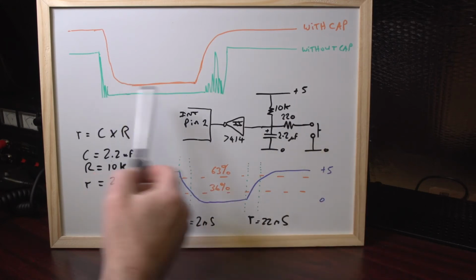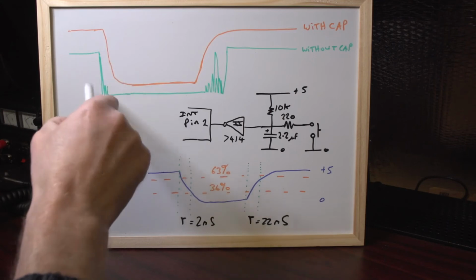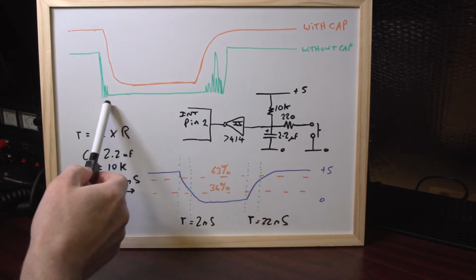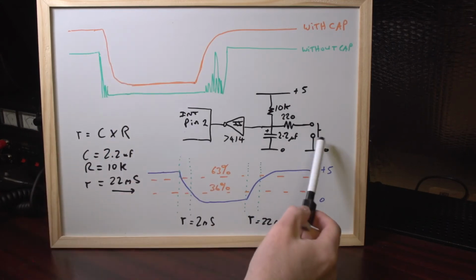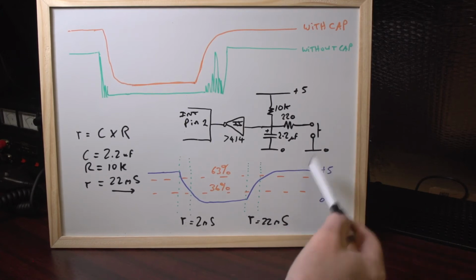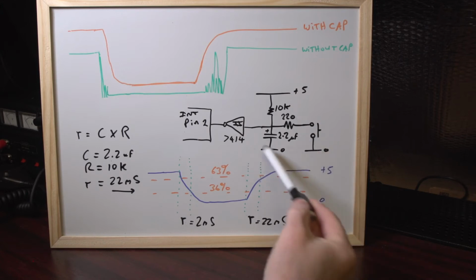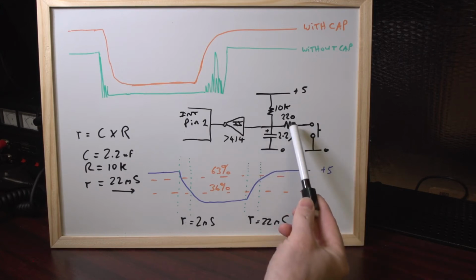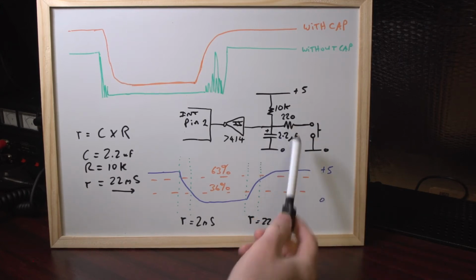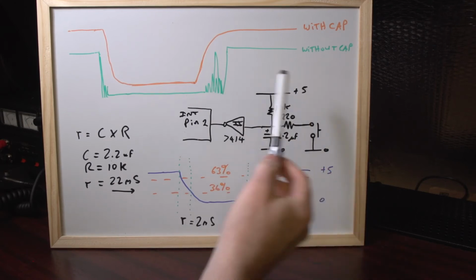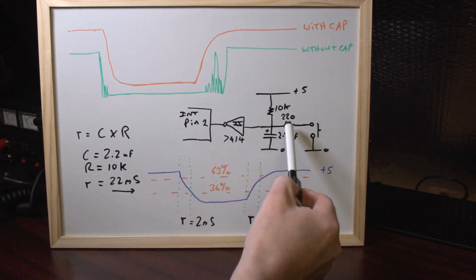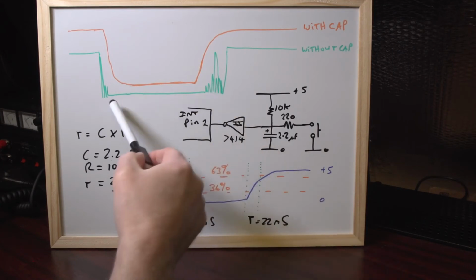It gives us a little bit of time constant on the discharge time when you press the button. It makes this a little more filtered out, and it saves the button from being degraded over time. After a lot of presses, those contacts would effectively be pitted because of the current flowing through them. So that's actually doing two things, and you could experiment with that value. That's the time constant, that's the filter circuit, and the button protection, if you like, as well. This is taking out these areas here.